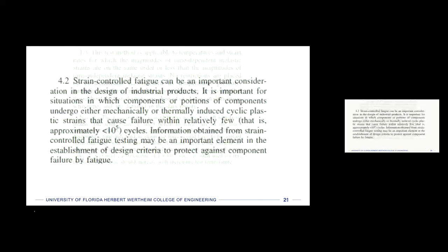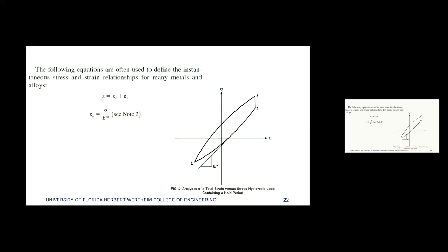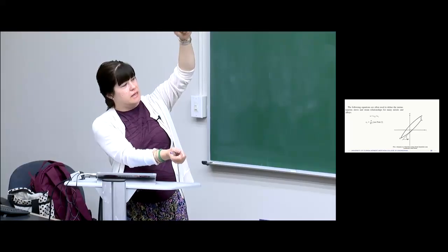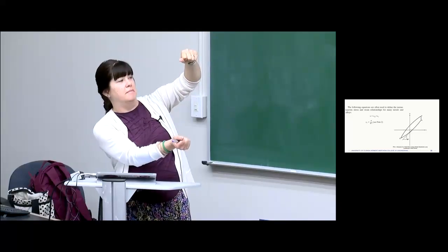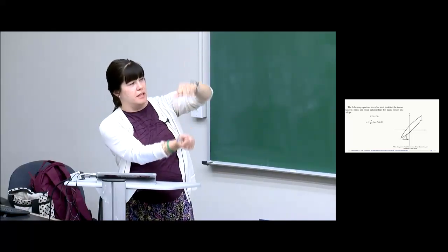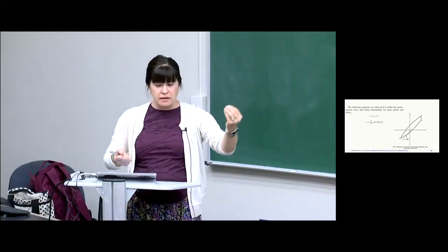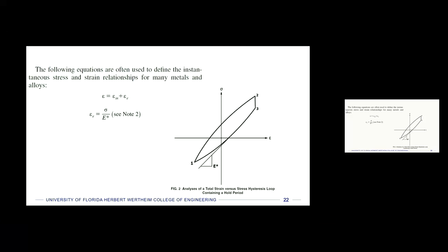And so I know we're out of time for today, but I'll end on this slide here. So this shows you a plot, and we'll be looking at a lot of these plots. This is stress and strain. If you start at 1, then you load a sample up, and then you let it stay at the same strain, but the stress relaxes, and then you unload the thing, right? So we'll now have to deal with dwell times and time-dependent behaviors interspersed with time-independent behaviors like elasticity. And so we'll talk a little bit about that in the coming weeks, all right?